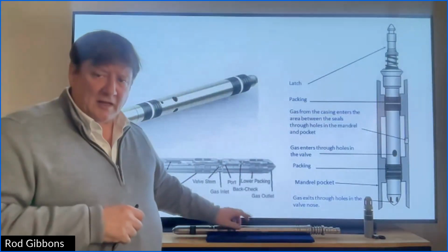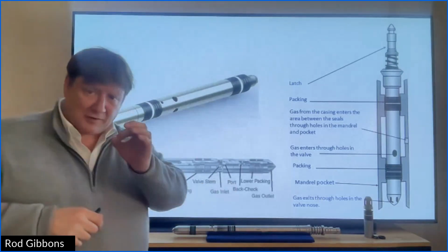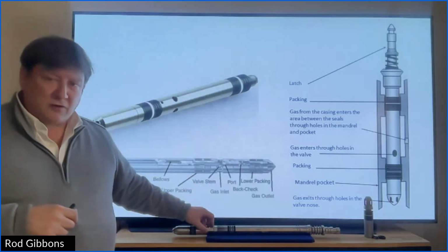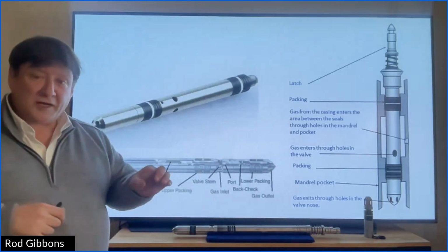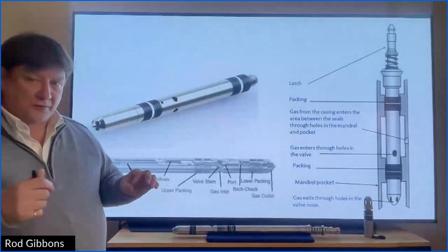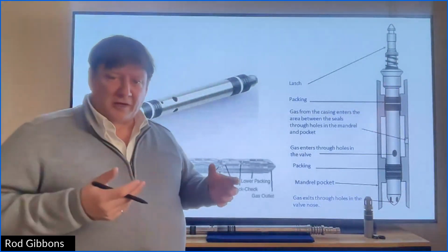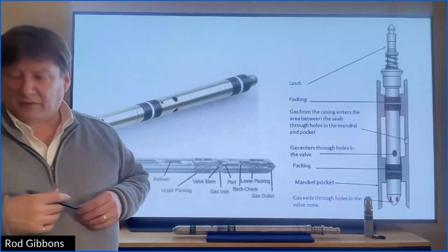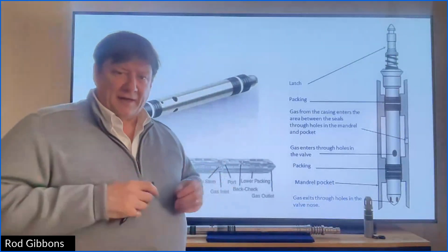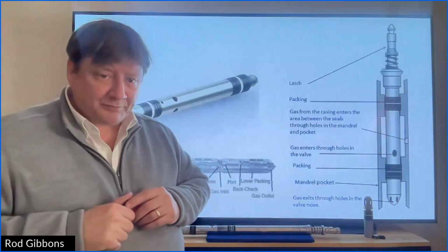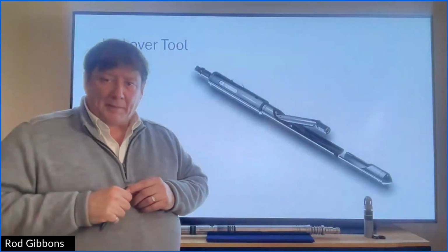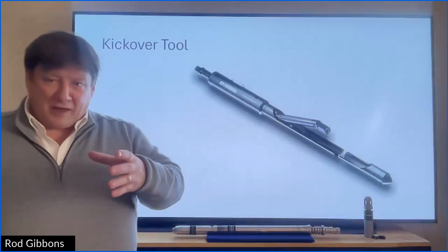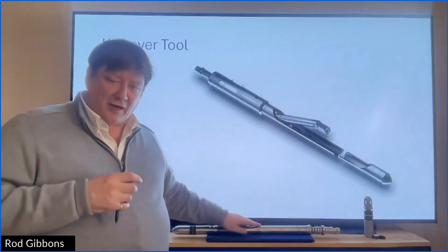And this is a 1.5 inch diameter. You can get gas lift valves in 1 inch for smaller flow rates or different well conditions, but 1.5 inch is definitely the most popular. So we've got our side pocket mandrel and we've got our valve.